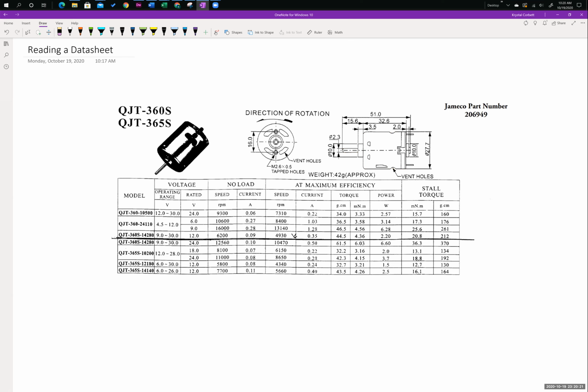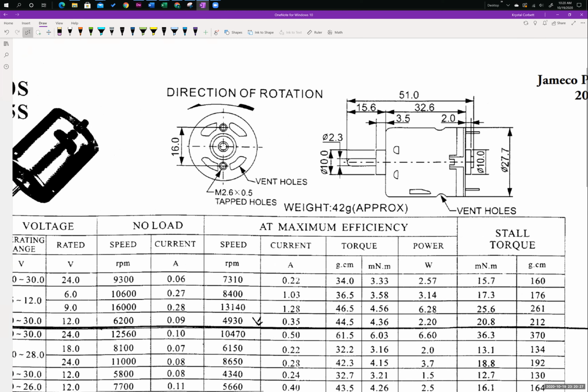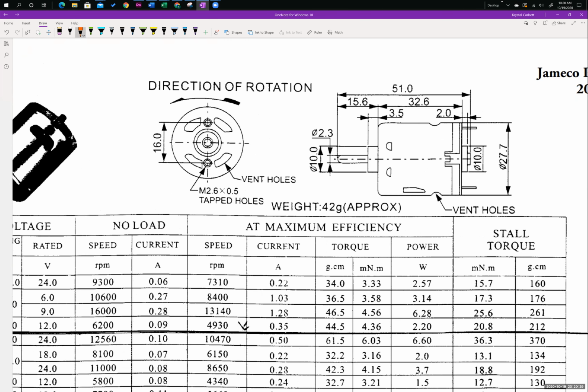Now, in order to understand what's going on with the pump body, let me zoom in and show you. We have these dimensions that are written here, and you can see it's drawn like this. So let's start with this far one right here. This one is showing you 51.0. Now, it doesn't have any units. I mentioned in the homework that the units for this is millimeters. And so all of the units for these numbers that are on here are millimeters.